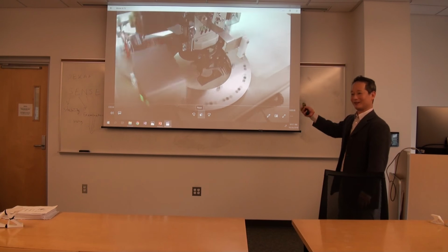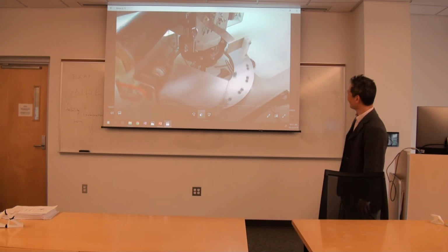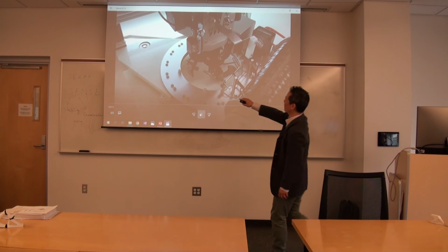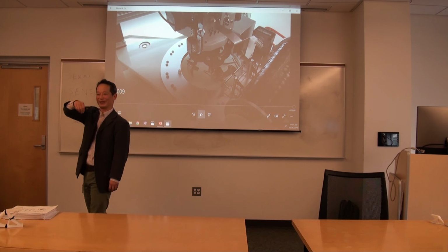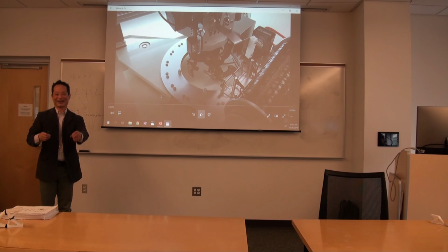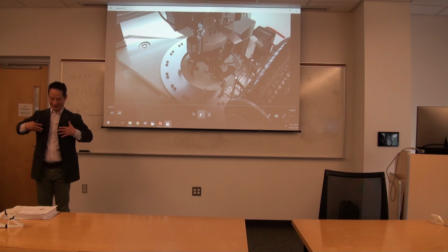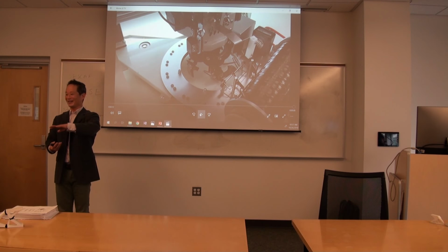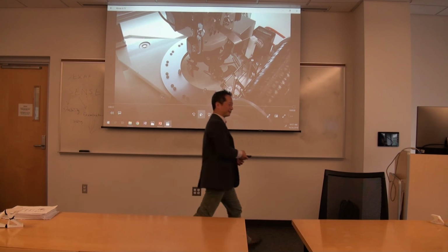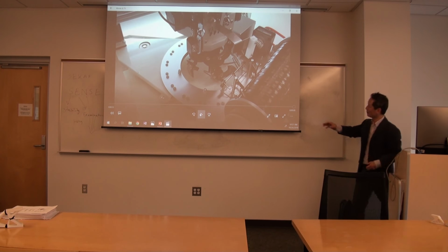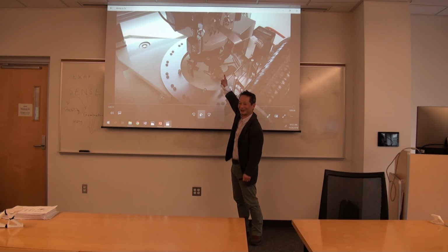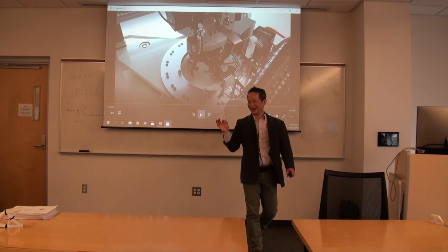So this is like doing embroidery, right? But this black one is carbon fiber, okay? And it is indeed a fabric. You are doing embroidery, but with thread made of carbon fiber. Now you have the carbon fiber embroidered fabric, and then you soak it into the resin and then mold it. If you know the fiber composite process, this is an amazing degree of curvature you are doing, which nobody actually does.